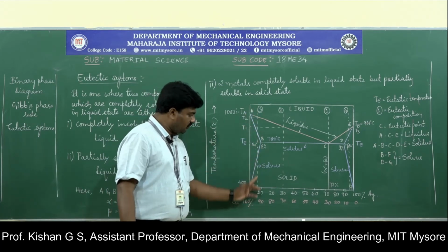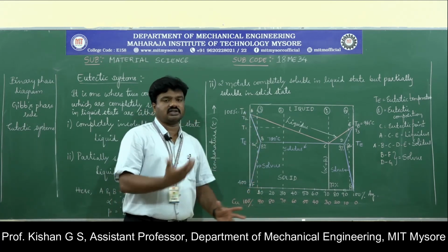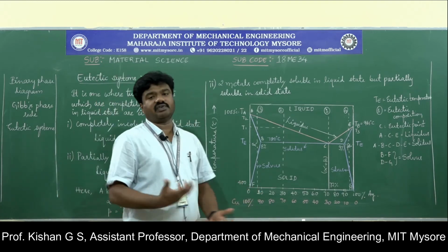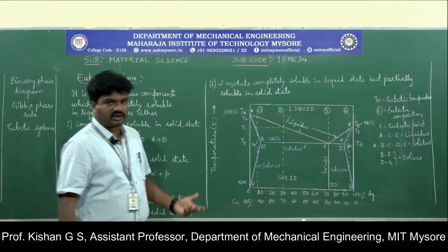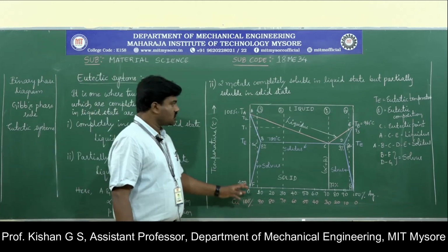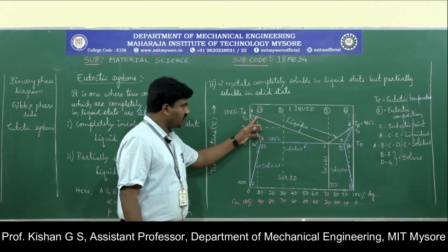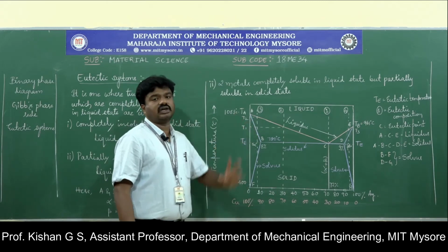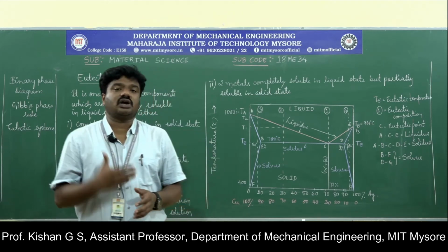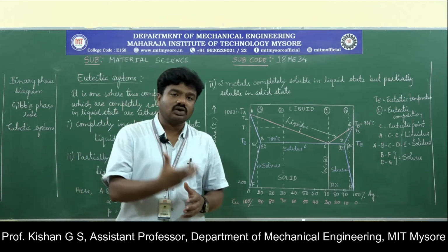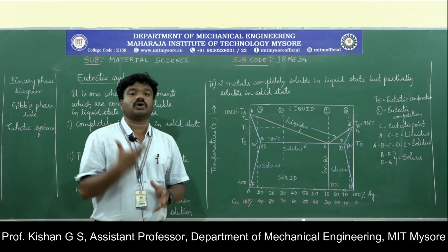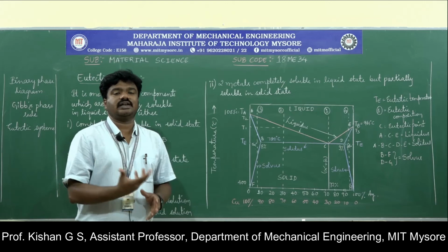With respect to the composition, say for example, we have taken around 5% of silver and 95% of copper for the assessment here. With 5% and 95% of composition, what is happening? The corresponding temperature leads to T2 degrees Celsius. T2 degrees Celsius results in the solidification of the copper material, that is, material A in consideration, being in progress, or initiated.